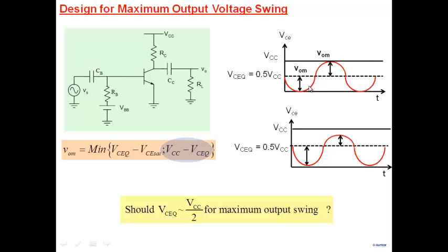So how do we go ahead and develop a better equation? Well, what we have to do is bring harmonic distortion into our picture here. The reason we are deviating from this particular picture is harmonic distortion. Positive swing is much different from negative swing here. So we have to bring harmonic distortion into our consideration of maximum voltage swing.